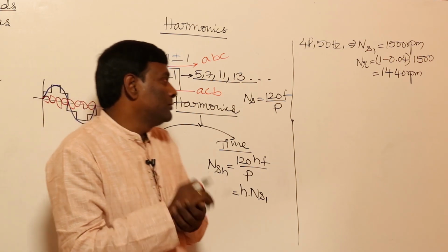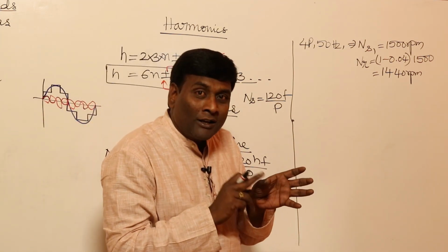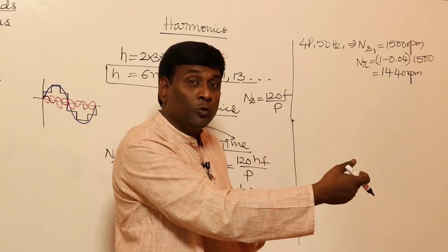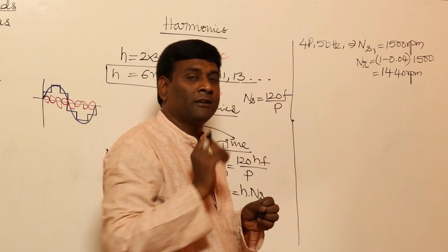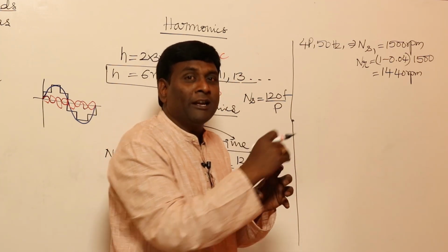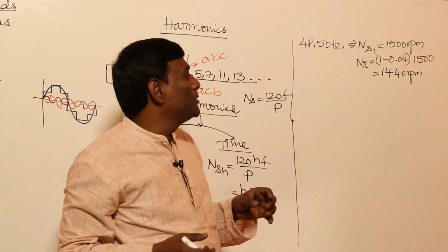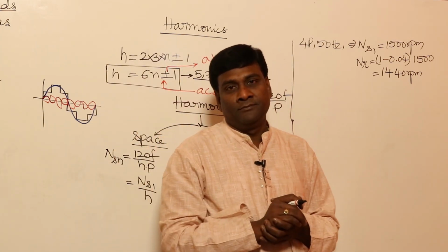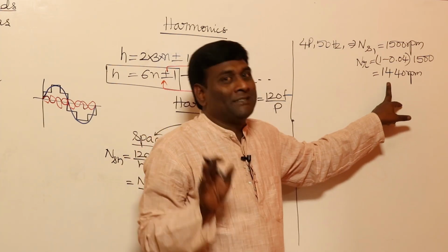Now the point here is, if you think of the rotor, the virtual poles can rotate in any direction because those poles are virtually created by the stator. But the rotor has to rotate at only one speed. Some part of the rotor cannot rotate at another speed, because it is a physical object. So the rotor speed will not be changed.